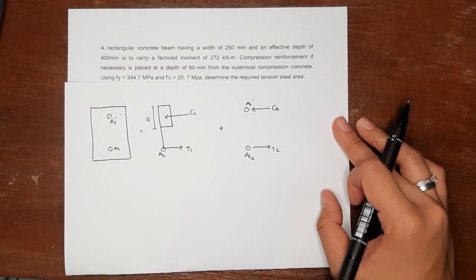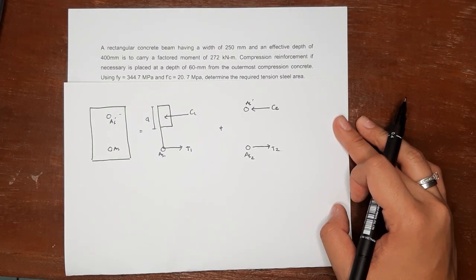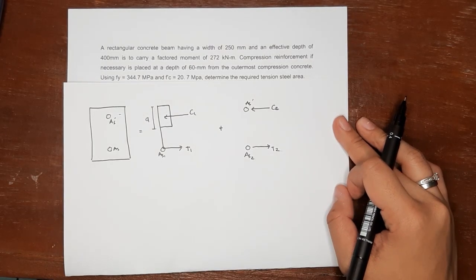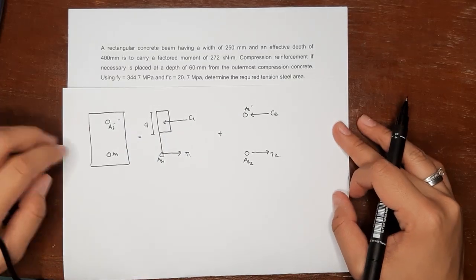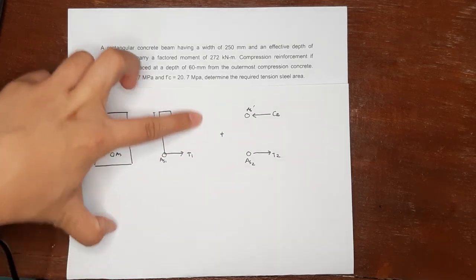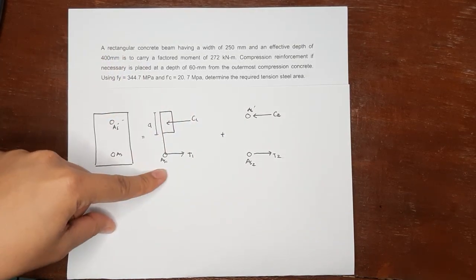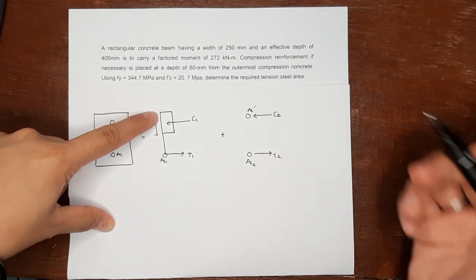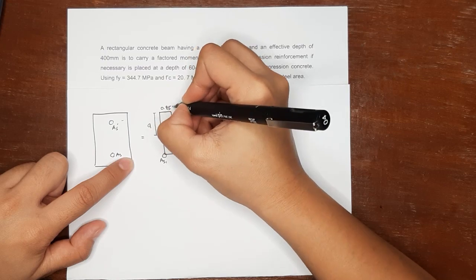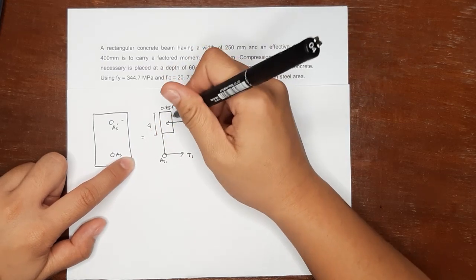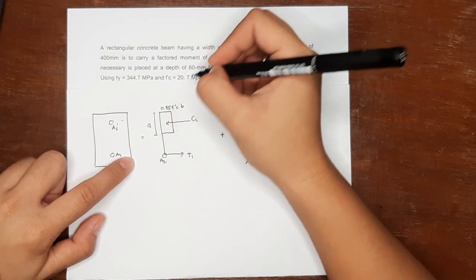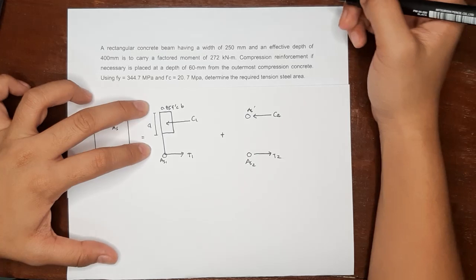Okay, since we already know that the reinforcements in both tension and compression is yielding, we are now ready to solve the area of our reinforcement. So we will have a two diagram. The first one is like a singly reinforced diagram that we have your compression block, which is the width of the compression block is 0.85 F prime of C and its depth is B. So this would be multiplied by B. Then the height is A of our compression block.